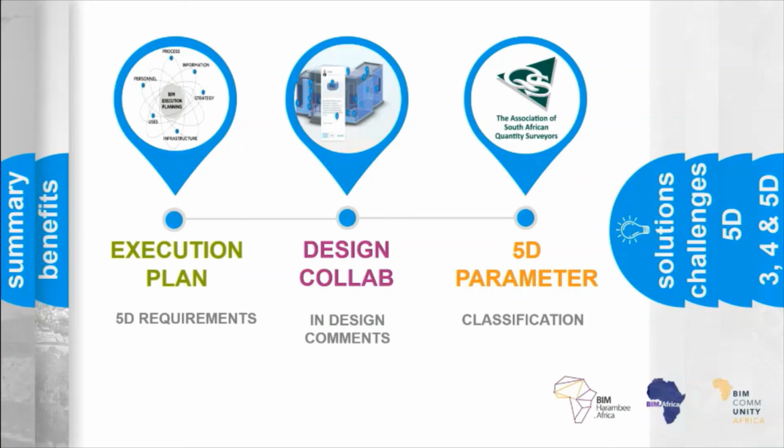And in order to undertake this task, the quantity surveyor will need to be included in the design workflow, so as to apply the classification to the model elements at the appropriate time and to the appropriate model. Now, this classification then allows the quantity surveyor to later extract quantities from the model according to the data applied, using different search criteria, and automated measurement formulas can be defined in our chosen measurement software. And as the classification is applied to federated models that the design team are working on and will continue to develop, the code then lives on in the model through the various stages of design. So that reduces the amount of rework associated with managing revision control and checking existing codes and applications. So we simply make sure that all objects are coded with the correct code. And if a new item is added to the model, we apply the code to that.